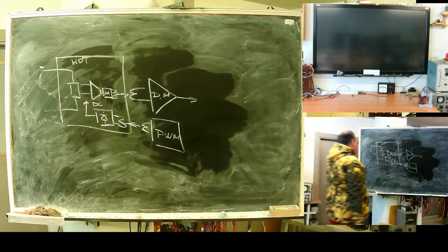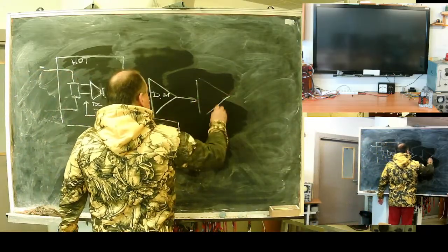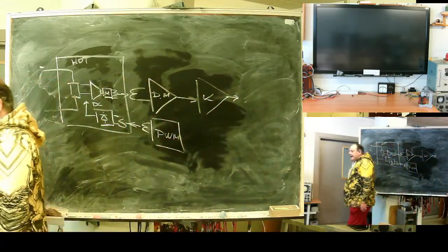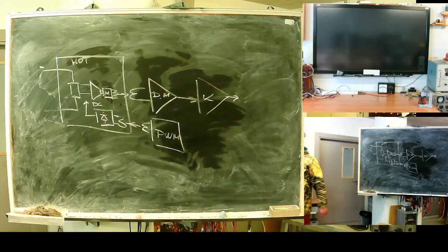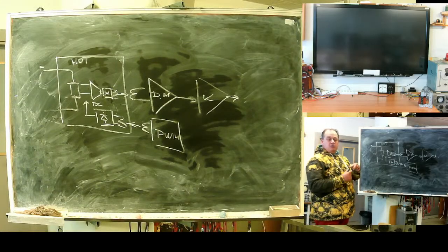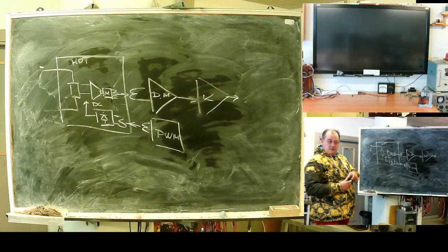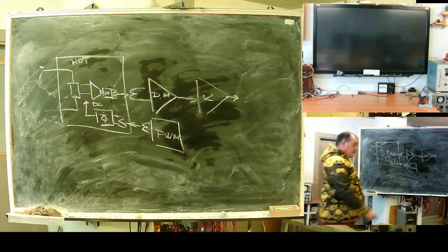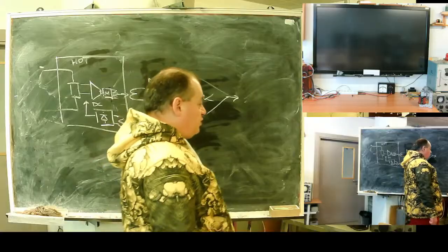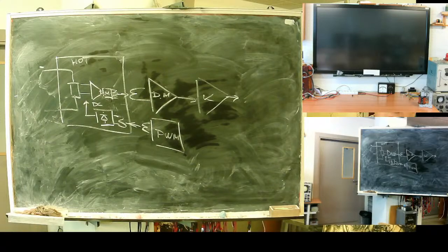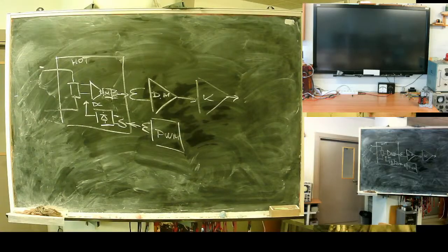The modulation, simple amplifier, you get your signal. On the market are available insulation operational amplifiers. Appears like an operational amplifier, like an op-amp, only approximately this size. Inside, two transformers, modulation, demodulation, PWM switch. Here, only the initial analog stage is performed on the hot island, and then signals in analog form go through.